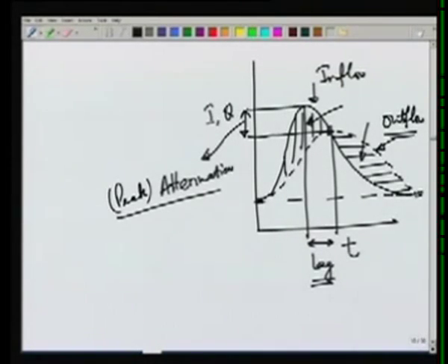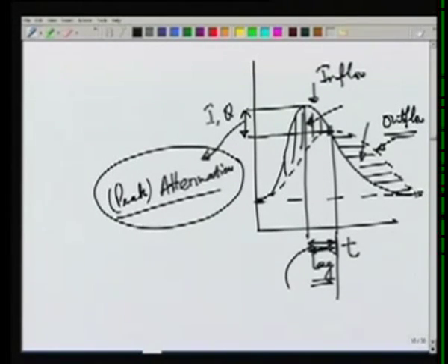So this has important implication in the sense that the flood at the inflow point is occurring at some point in time, but it will have some lag as it passes through the storage reservoir. So the peak will be reduced and there will be lag also. So there will be an additional time to peak which the downstream locations will get. So these two are important in the sense that how much peak is reduced and how much extra time we get will affect our preparation for protecting against flood on the downstream side.